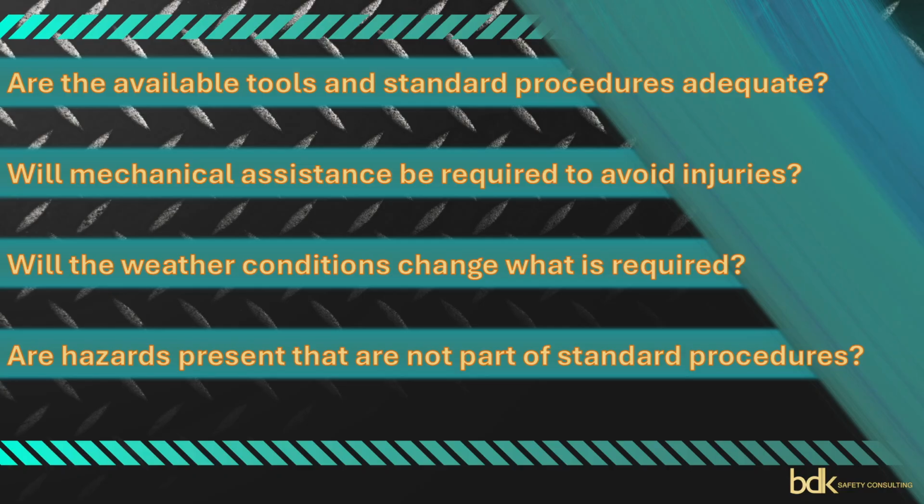Breaking down the work into these separate tasks will ensure that each step is properly assessed. However, adding a task for cutting the banding from the lift of studs is where we would cross the line into micromanaging the assessment. That should be common sense. Next, we will look at the hazards.